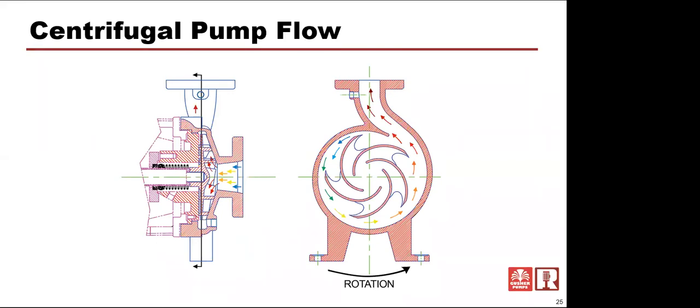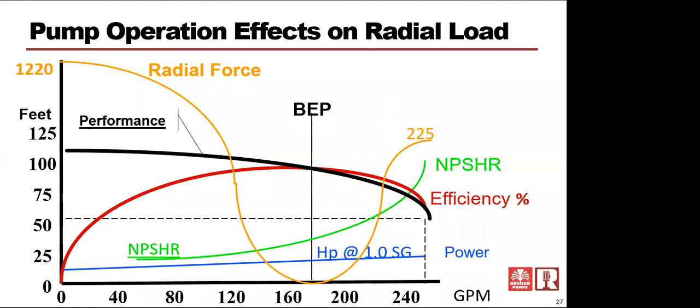And if you're forcing 30% of it back across the front side of this impeller, what is that? That's 750 pounds of fluid that you're trying to relieve. There are going to be bad things happening inside this casing because of all of that movement and turbulence. And again, we're going to talk about cavitation, and that's going to be a major part of that conversation.